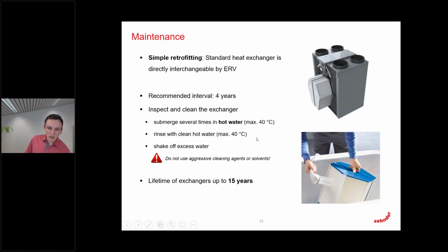Let's also talk a little bit about the maintenance, which is equal for both exchangers. You just need to open the unit and then you can remove the enthalpy or the heat exchanger. By the way, they also said it in the video, if you want to upgrade your unit, this is simply possible because you can just change the HRV to an ERV. There's nothing else to do. You just need to confirm in the unit setup that there is an ERV installed now instead.